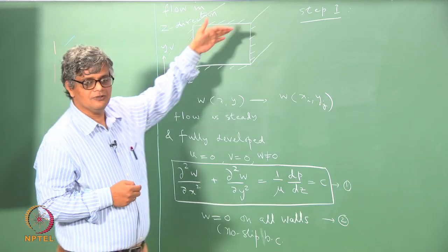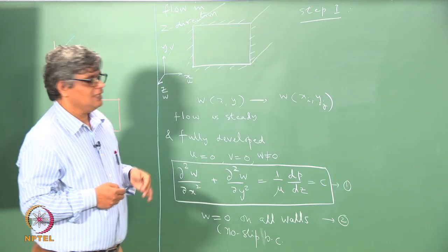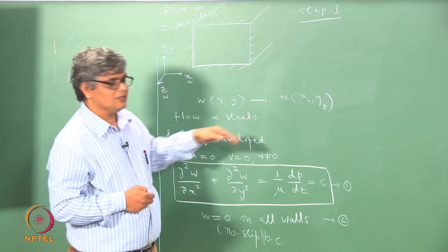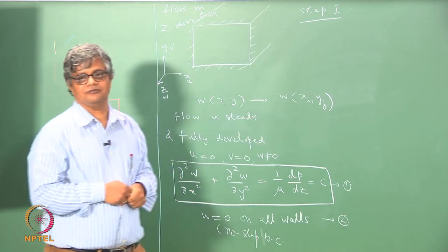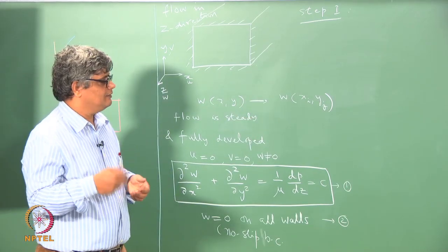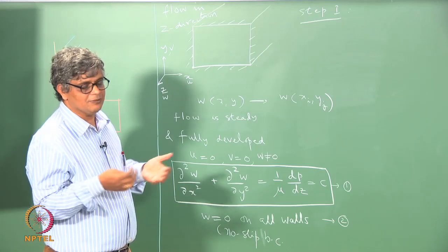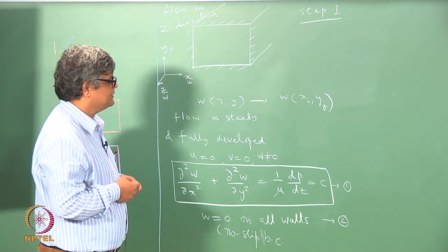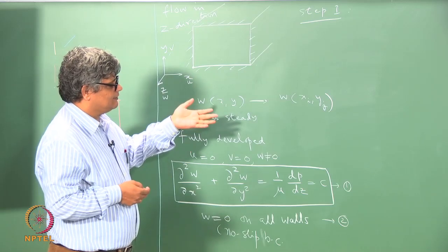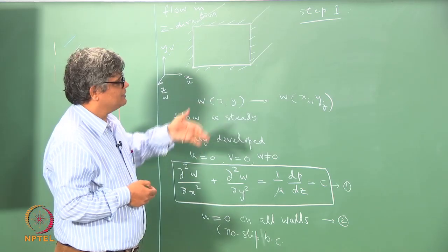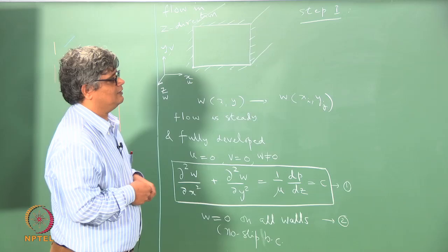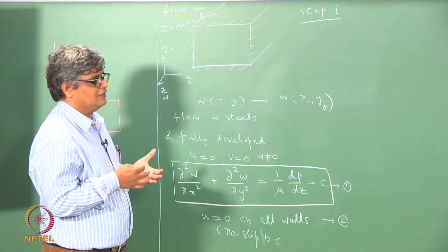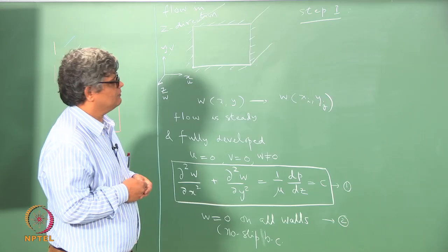In the first step of the CFD solution, we identify the nodes, the grid points at which we will be getting the solution W. It is in our control. We will see later on that we can make as many grid points as possible given all your computer constraints. So, we specify the grid points, and that is the first step of the CFD, which we can call the discretization of the computational domain or flow domain.